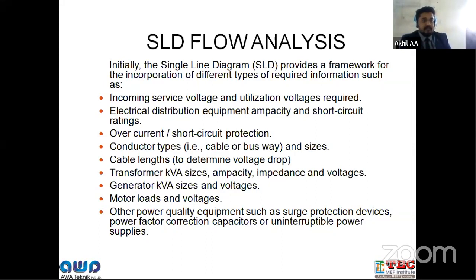If it is a bus bar, you will be mentioning the bus bar thickness and width. Okay, and also you'll need to provide the voltage drop calculation. If the cable length is a little more, like more than 100 meters, you might have to do the short voltage drop calculation in the SLD itself. Okay, then the transformer size, generator size, transformer protection, primary protection of the transformer, secondary protection of the transformer, and